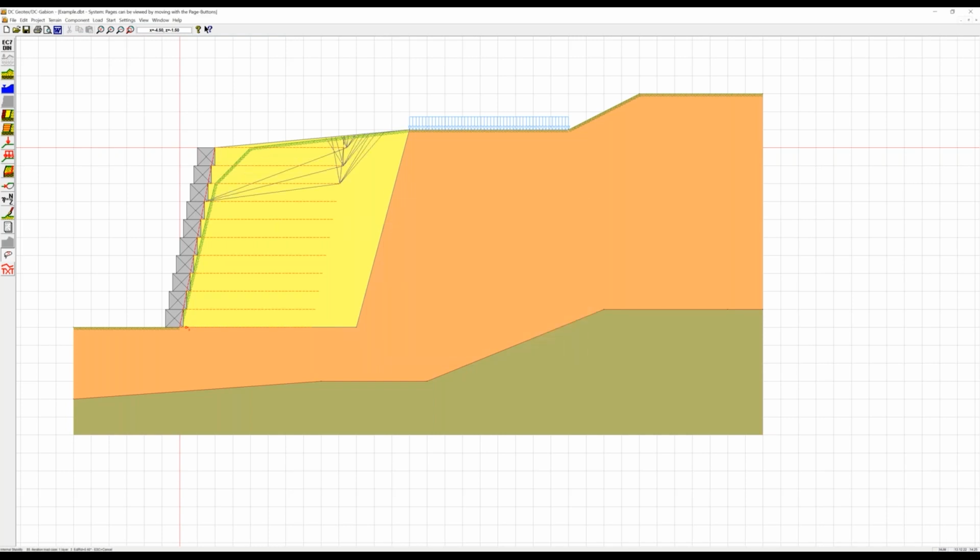And you see that all these different soil blocks are calculated for the internal stability. We are looking for the block with the least safety, the critical safety for this construction. And these geosynthetics layers may as well be lengthened if they are not sufficient. And up to this time now, it's still a sufficient length.